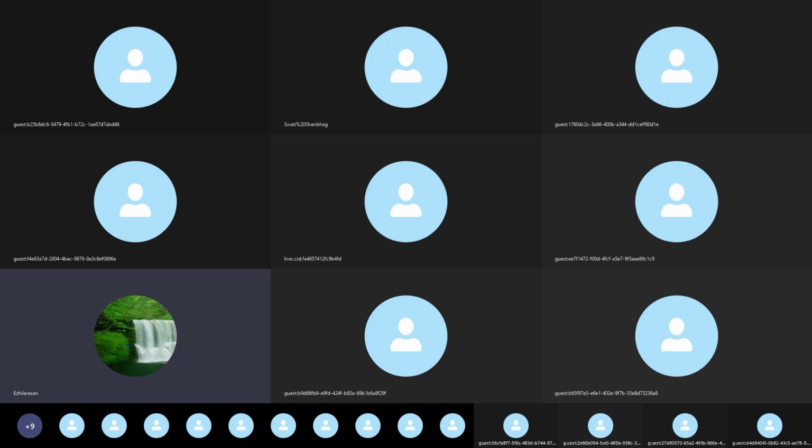Next, what we will do? Let us study the values of each delay. Verilog will provide an additional level of control of each type of delay mentioned above, like the minimum value, the typical value, and the maximum value. Keep it in mind, each type, in the sense we previously had rise, fall, turn-off. Now for each type of delay, we have three values.